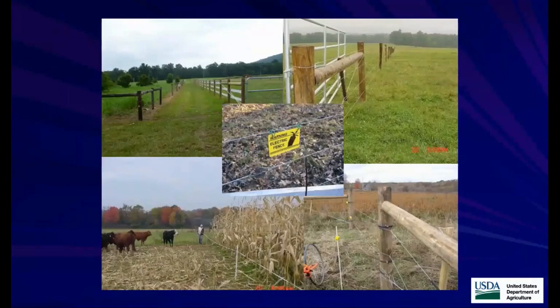The bottom right-hand picture is a high tensile fence, but it has some temporary gate material, which helps with animal movement and makes it easier than using a big metal gate. You can just use 2 strands of a temporary gate material that's electrified, and usually the animals will also respect that. Of course, anytime you electrify a fence, you want to have a warning sign on it, especially if you're along a road or a property line, to make sure that other people know that the fence is electrified and to reduce liability issues.